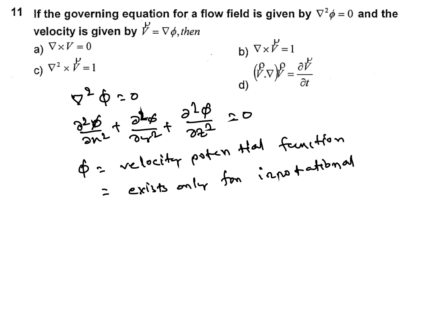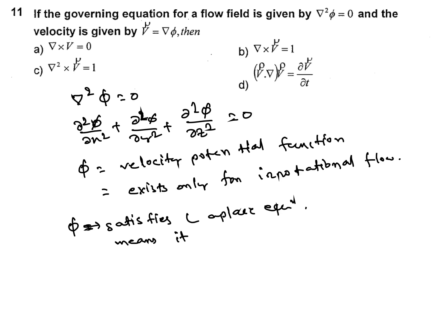And here, if velocity potential satisfies the Laplace equation, it means it satisfies the continuity equation, and the flow is possible.